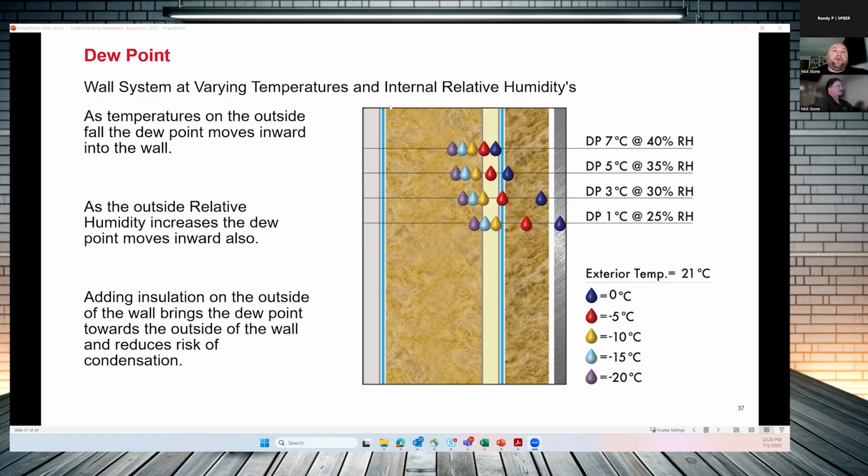No matter how much insulation we add inside of our wall cavity here, we're still going to have a weak point within our frame. For instance, insulation is about R-4 per inch, where our wood is about R-1 per inch. So our insulation is 4 times more energy resistant than our wood frame itself.